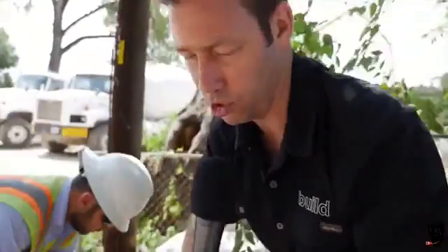A couple tips for you as we close out this video. You might see concrete with a really low slump, maybe a 3 slump. You might see really soupy concrete. If we're getting down to like 7, 8, that's when we need to think about not adding any water on the job site, because ultimately you're not going to get the mixture that you're going to expect from the plant, and your clients are going to end up having potentially more cracking in their foundation or other things.